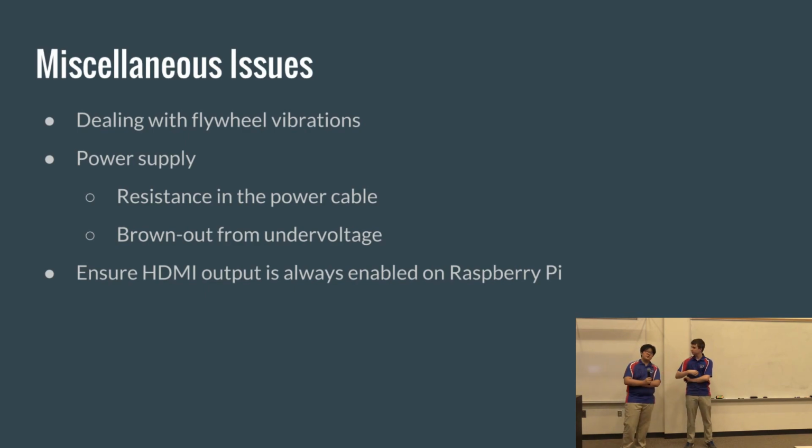So one of the reasons why I recommend Logitech cameras is that different USB cameras allow you to do different things to them. One of the issues was that we were trying to set exposure values. If you have auto exposure on a web camera, you can actually slow down your program quite a bit. So we wanted to have a set exposure value. But the Microsoft webcam was really weird in that it jumped all over the place when we tried to set exposure values. But when we started testing Logitech cameras outside robotics, they were much more consistent in terms of setting exposure values. So our recommendation is to try to use Logitech if possible.